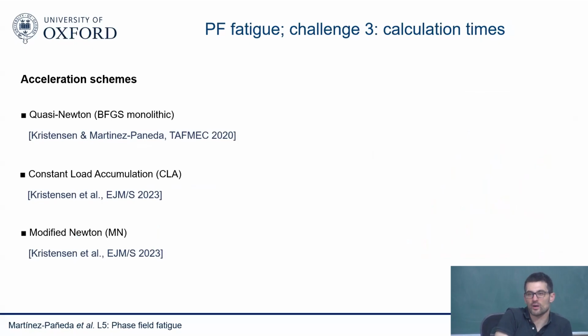So being able to run fatigue calculations cycle by cycle is very powerful from a predictive perspective, because very often, of course, we do our experiments assuming a constant stress amplitude, but in reality we don't have a constant stress amplitude, right? So we work with people, for example, in batteries where they charge electric cars, and they do have a history of loading, but every user charges their electric car in a different way, so the battery is exposed to a completely different cycling history.